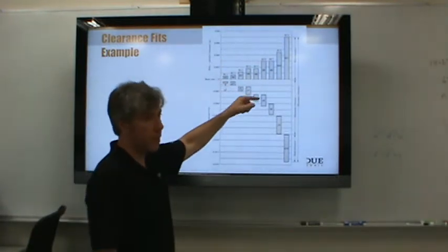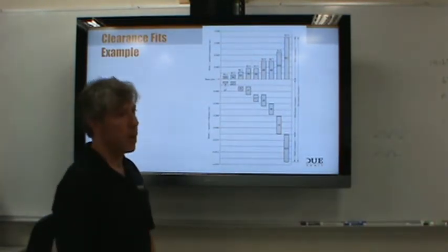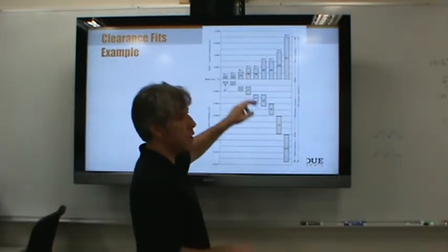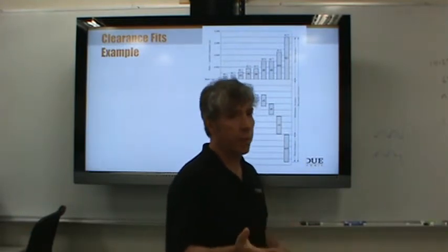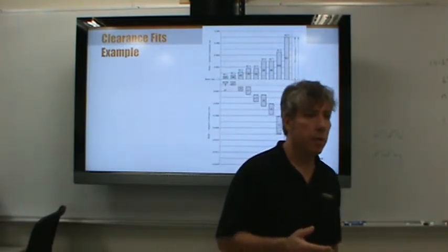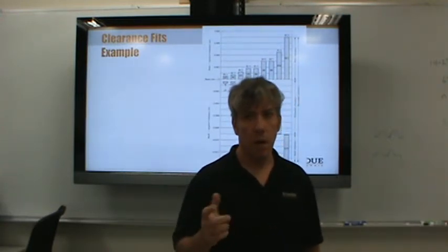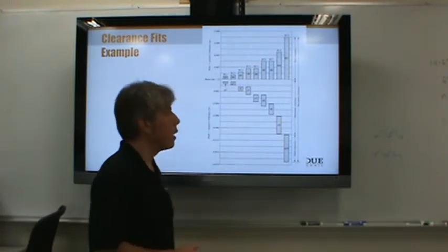That's more common in metric, although you can technically use these for English sizes. But even on drawings, it's very rare to say I want an RC3 fit on this. Nominal size, 2 inches, give me an RC3 fit. The machinist will be able to look it up, but most of the time, with the tools we have today, there's no point in doing that. The best thing to do is simply put the tolerances on the part and look it up yourself, that way you're controlling.